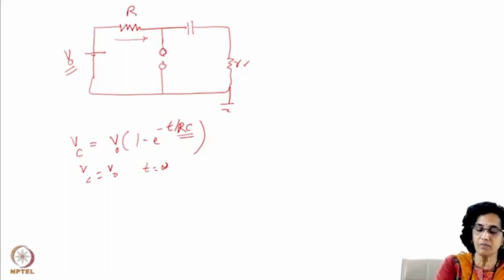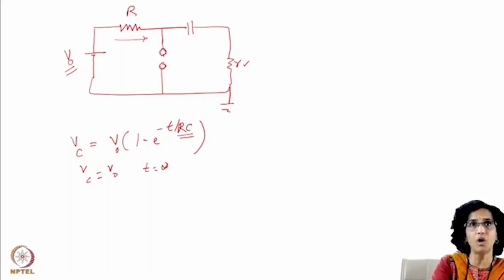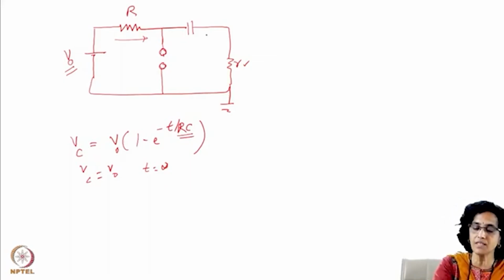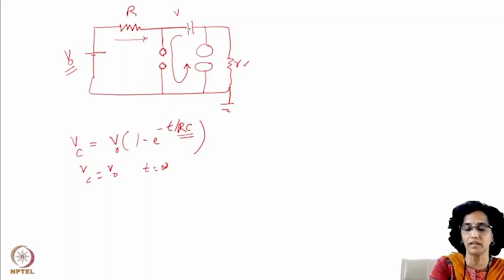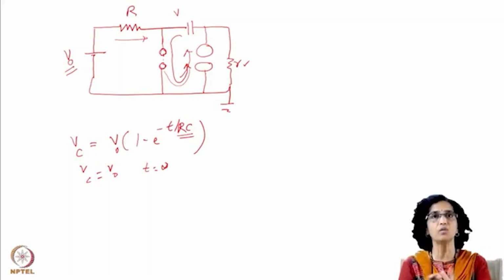And the separation between these gaps is so arranged, so adjusted, that it is the voltage that you want the laser to switch at. And so this condenser then switches through a laser load. I'm just showing the laser load as, again, two electrodes. So once this is charged to the required voltage, the switch closes. When the switch closes, the condenser sends the energy that is stored in it in the form of current through this conducting switch into the laser loop, right? So you have the discharge of the condenser into the laser load, creating this current.